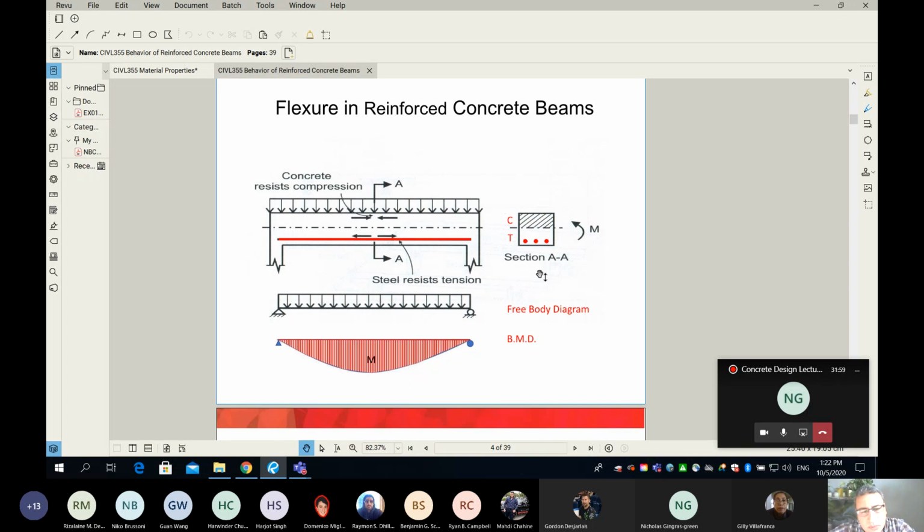When I apply a uniform load, as you see on my slide, on a simply supported beam, this will cause a bending moment, or cause your beam to bend. And the bending moment diagram is not new. You've seen this last year, and you've seen it one more time in my class this year. It is going to be a parabola. Whether you draw the parabola on top of your beam or at the bottom like I do on my screen, both are right, and the value is wL squared over 8.